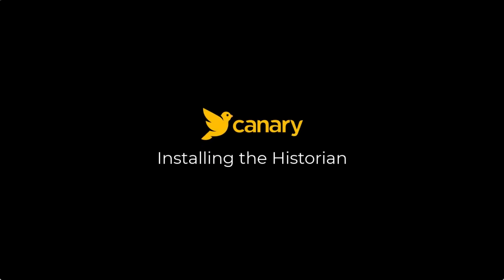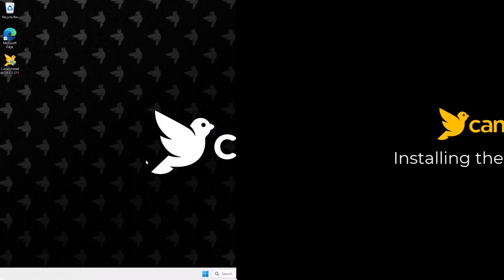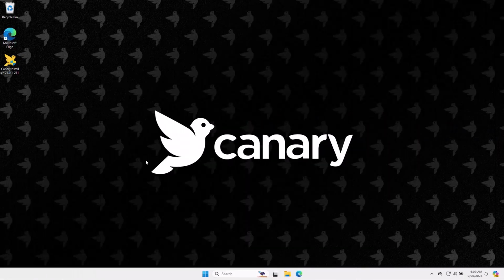All right, in this video, we're going to learn how to install the Canary system, and we're first going to take a look at the historian server. It's typically what you would install first, with the components that are involved with it. It's also where you want to install the identity service, so that has to be the first machine that you install something on. It has to contain the identity service because other services have to connect and communicate with the identity service if they're remote. So we'll step through that as we go through the install.